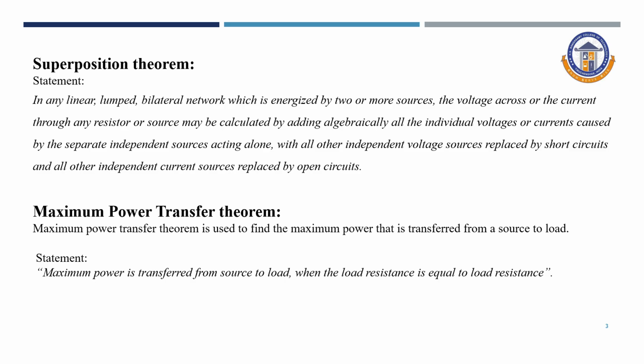Third source activating alone, what is the response. Then I take the algebraic sum, not just a sum. If you are measuring the current, the current direction may change, plus or minus. So the algebraic sum gives the resultant response, which is equal to the response when all three sources are activated at a time. That is your superposition theorem.